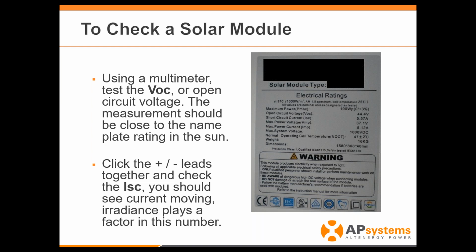But this is a great way to be able to troubleshoot a module, use the amp meter to be able to say that it's not an inverter issue, it actually was a module issue. But that gave that customer, that installer, the ability to see that quickly and easily and resolve his customer's issue very quickly.